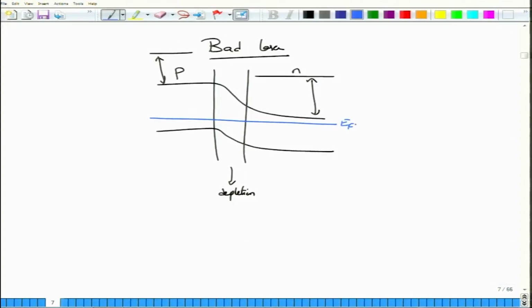But when the PN junction is forward biased or reverse biased, the junction is not in equilibrium. When the junction is not in equilibrium, I cannot talk about a single Fermi level. Rather, I should talk about what is called the quasi Fermi level for the holes and the quasi Fermi level for the electrons. And you have to dope both sides heavily, with large amounts of acceptor and donor atoms, so that this Fp, which is an abstract quantity, can be brought inside the P region valence band, and this Fn can be brought inside the conduction band. This is a very important thing for lasers to have.